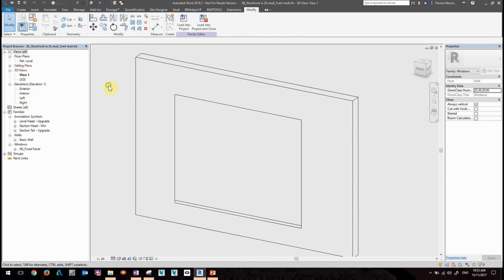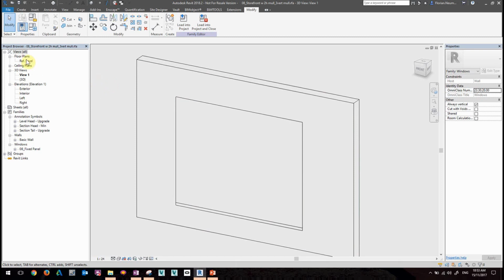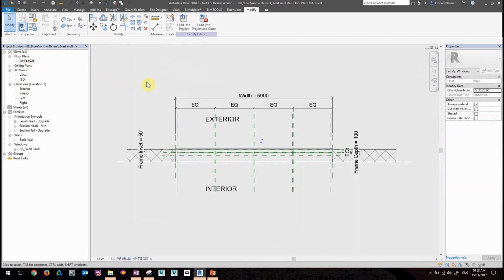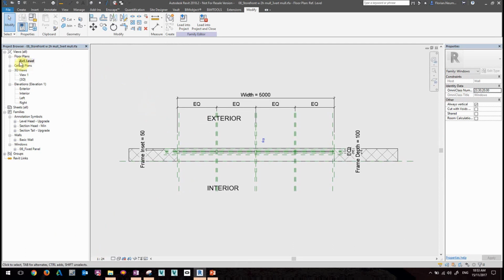So when we model something, we also want to constrain it following ANZRS. Anybody heard about ANZRS yet? Australia, New Zealand Revit Standards. If you don't have them, just copy them. You can just go to www.anzrs.org. So we have there a bit of a pattern on how we constrain families, first from the plan view, then from the front, and then from the left.